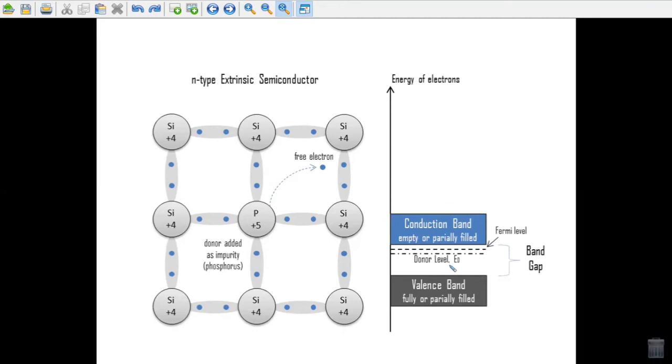so between the valence and the conduction band, these levels are at a distance of EA at about 0.011 electron volt above the valence band. At absolute zero, all these levels are vacant, but at any temperature above, electrons from neighboring atoms can fill the vacancy, thereby leaving holes in the valence band. They establish bonds with the indium atoms and lose their ability to move in the germanium lattice, and hence do not take part in the electrical conductivity.